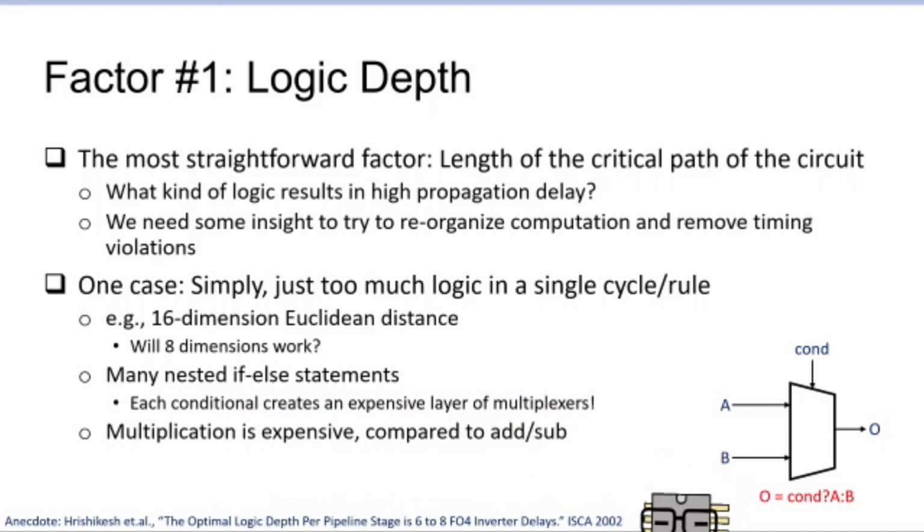That's how stringent this is. That's why back in the era of Pentium 4s and whatnot, we had really, really deep pipelines. But now it's kind of back to like, I don't know, 17 pipeline stages. But then we had CPUs with 50-stage pipelines because of these restrictions.